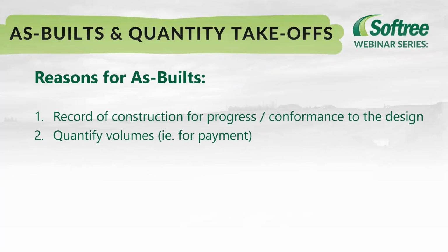Okay, so today we're going to focus on as-built estimation and quantity takeoffs, and there are a few reasons why you might be doing this. First, as-builts can serve as a record of construction for performance or conformance to your design. Second, they're great for helping you quantify volumes, for example, for payment purposes.